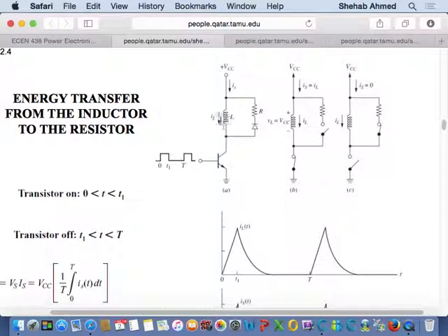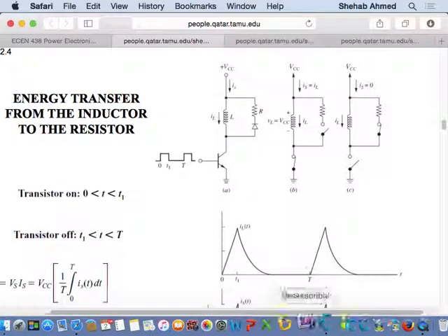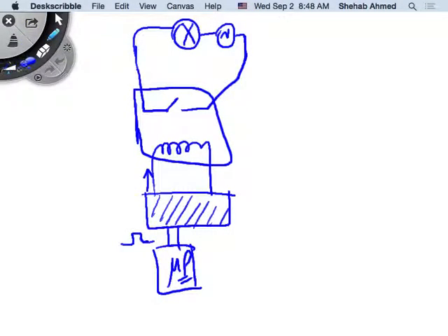So a relay is a good example because for a relay, the input is basically an inductor, and typically you would put around the inductor a circuit like this, because you don't want to open up the relay. Here, I didn't do that. Yeah, so you don't want to open up your relay contacts without having this diode and resistor around it, because in that case, what's going to happen?